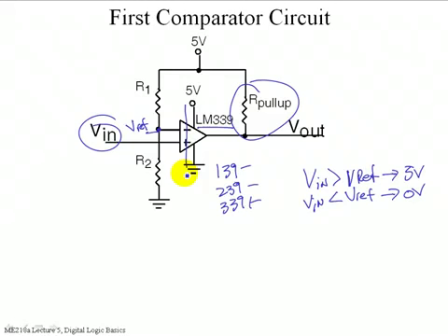But we are not going to operate comparators in negative feedback, so we can't apply the golden rule about the inputs being at the same potential because that requires that we be operating the device in negative feedback. So from a circuit analysis standpoint, no current in or out of the inputs, that's good. We're going to keep with that. Yes.